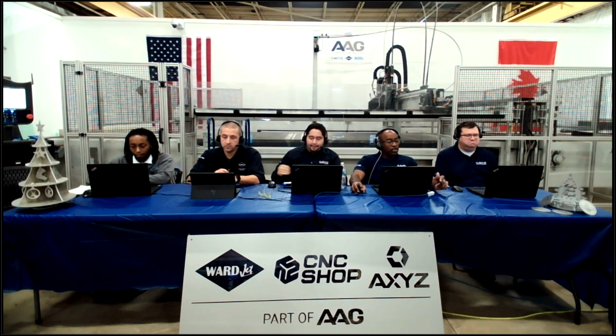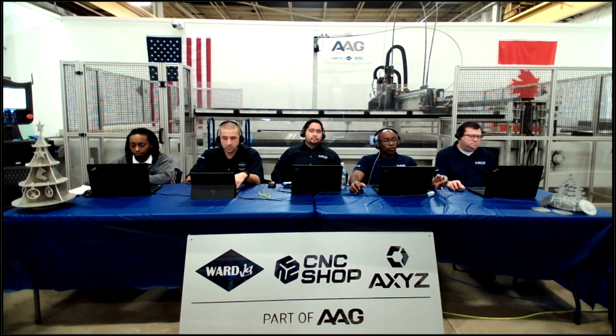Okay. Thanks, Kevin. How does the misting fluid affect foil boards? Typically it does not. You're basically blowing a mist onto the tool. On our system, our wands for the mist are fully integrated into the dust collection booth, so that when you're running the job, you're blowing mist onto the tool, collecting the chip, and also pulling up all the extra mist that's being applied. So you may get some staining on the board, but it's not going to affect how it operates or the vacuum that you generate through the spoil board when using the mister.